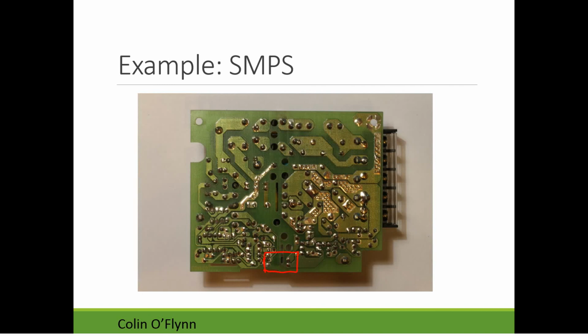You also see slots in the circuit board. These are to prevent voltages from arcing over. So you see some slots here, and there's one under the opto-isolator as well. So opto-isolators can be seen and used as a form of buffer. In this case, we're not using it necessarily for the circuit loading effect, but for buffering one side of the circuit entirely from another, with no concern about voltages crossing it. But the objective is the same. We have an input on one side, and we want to have the output on the other side.